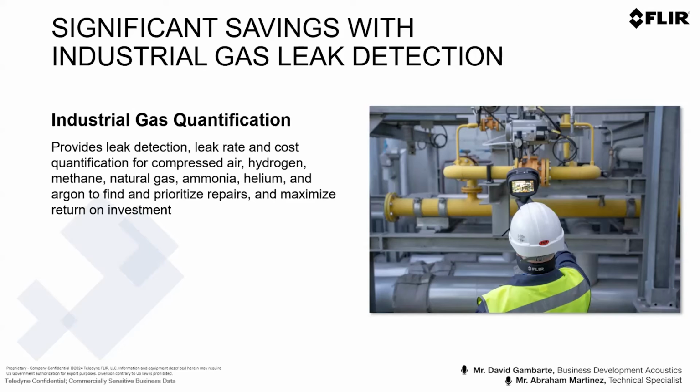And if you compare the gas density with the compressed air density, which is around 1, you will be able to more or less estimate the difference between one leak size and another. So in any case, you will be able to find the gas leaks in your premises, even though they are not listed here.